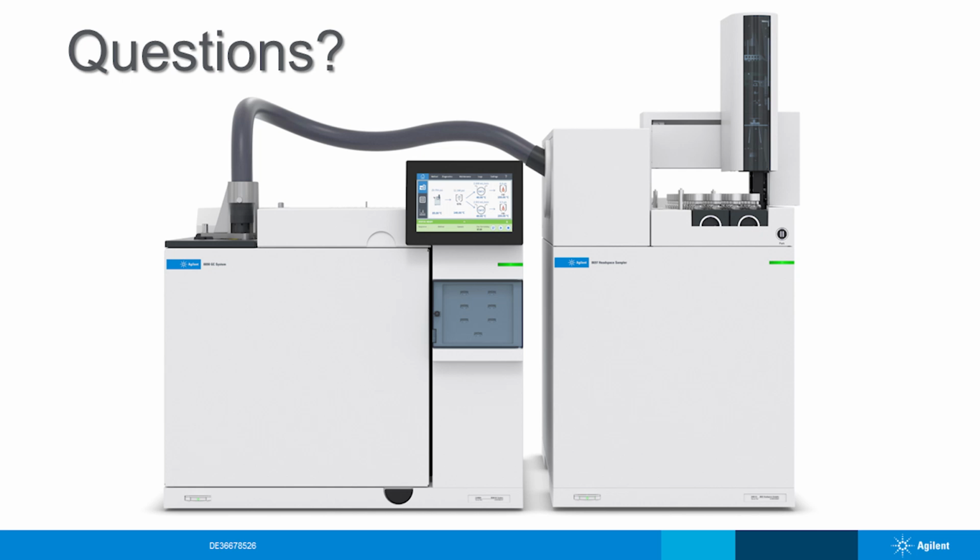I know that sometimes we face budget constraints, and that type of thing is problematic, especially for research labs, academic labs. So if you have to reuse the vial, you clean it and then certify it with your headspace that you actually did get it cleaned. But always put new caps on. So again, I strongly advise against it, but you need to verify that your cleaning process is good, and always use new caps. I don't know, Adam, do you have a comment on that one?